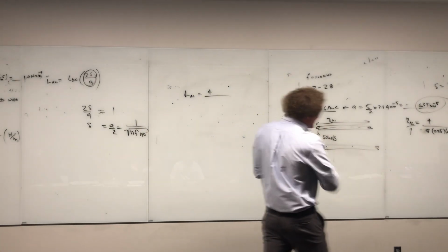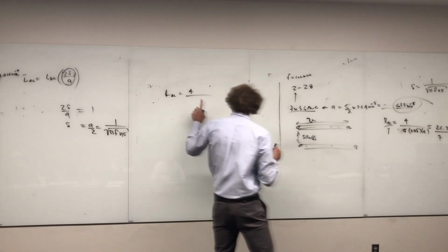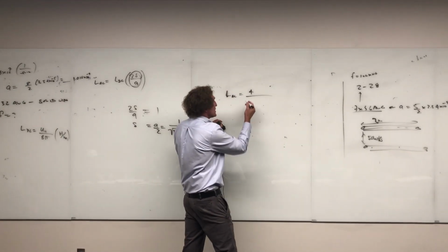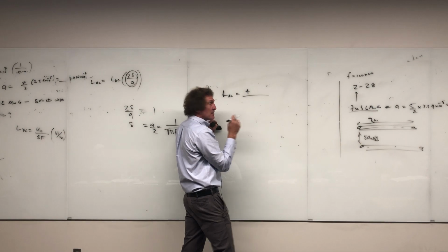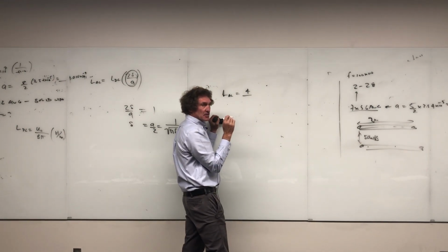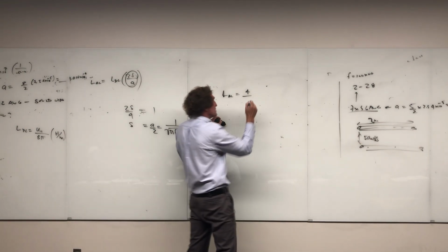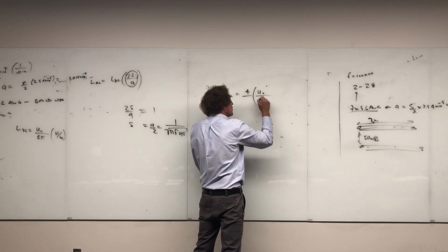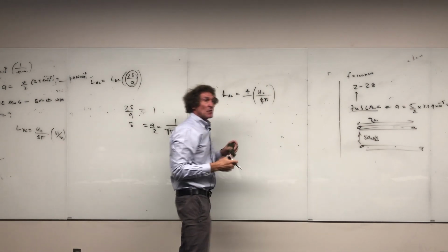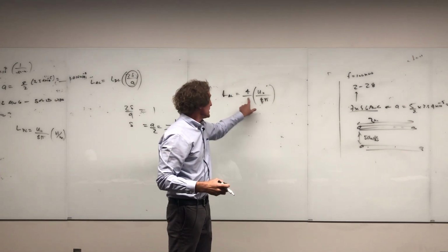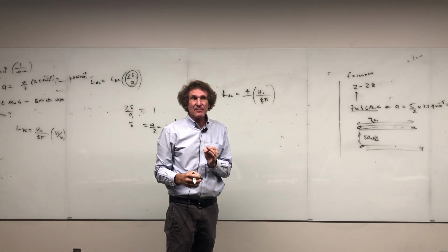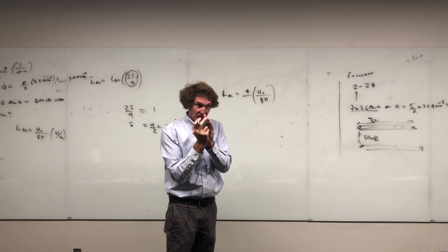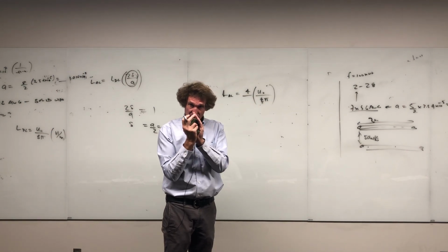Anyway, getting back to this, it's going to be 4 meters, right? And now we're going to put in the DC inductance. I'm just going to get the DC inductance: 4 meters times mu0 over 8 pi. Now that's the inductance, what? Henries per meter times meters is henries, right? That's DC, correct?